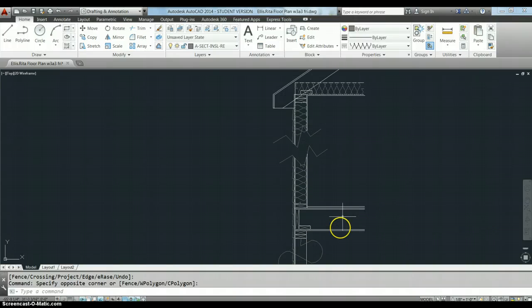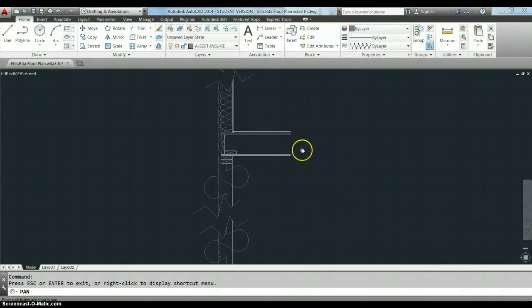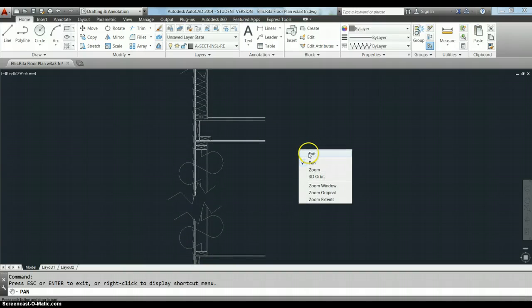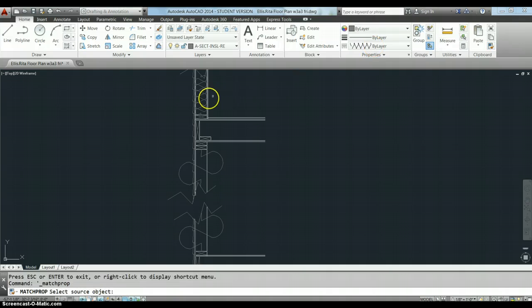But you do need to go ahead and show, they may have put a piece of 1/2-inch plywood on the bottom of that joist in order to provide a little bit more acoustical isolation or to provide more rigidity, depending on how big the structure is or something else. It's a little unusual, but there are reasons to do that. Okay, and then once again, we're going to come back in here and match our properties for our insulation.